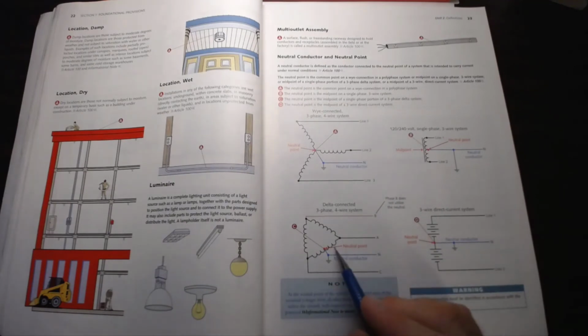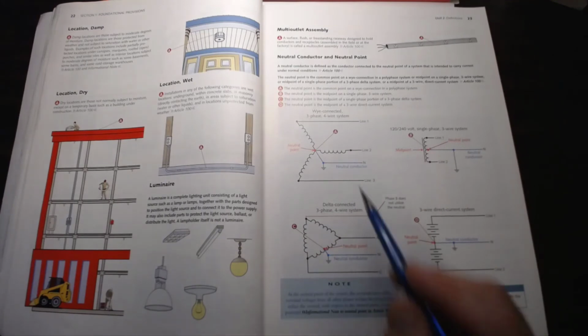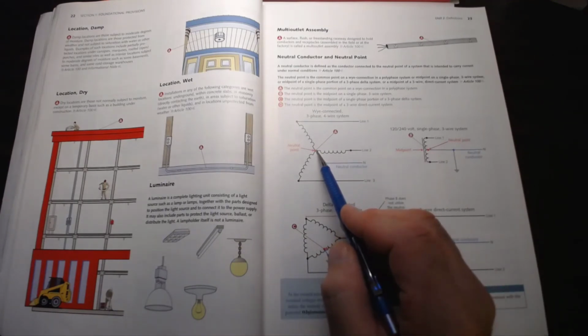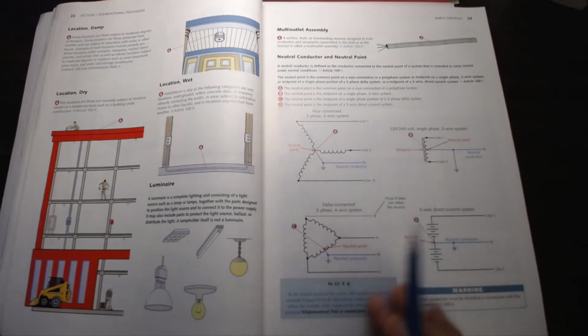These aren't as common anymore, but these were very common as industrialization occurred in the 1940s and 50s, where there was lighting load. There was a small amount of load for maybe an office, but the majority of the load was industrial, needing the 3-phase 240 volts. This transformer could be 120/208, or in some cases you can get 480/277 on a Y.